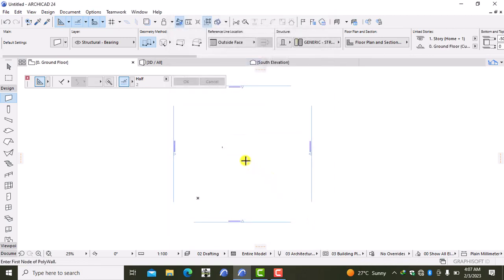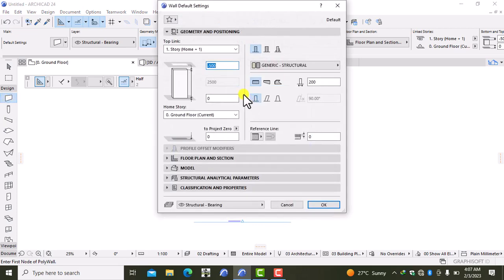So the foundation of every plan is to come up with the orientation of the walls of your house. So basically, what I'm going to do in this video, I'll be laying out the orientation of the walls of my plan. First I'm going to set the height of the wall. Originally we had it at 3000. When you open your ARCHICAD, you are going to have it at 3000. So I'm going to change this to negative 500, so that I have it at 2500 before later on I'm going to come and do the lintel or the ring beam, then later on do the roofing. Also have our wall thickness being at 200, and to project 0, so we can work with that.